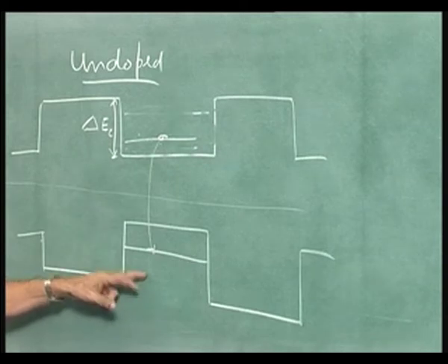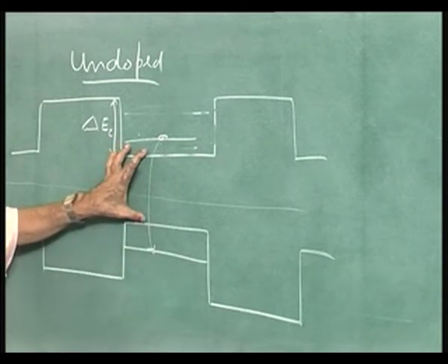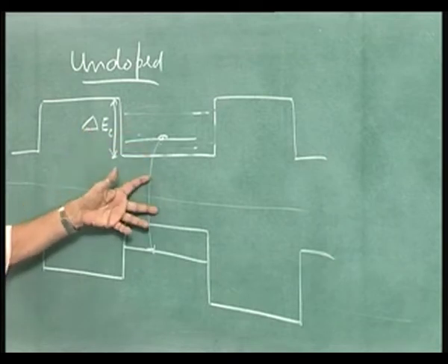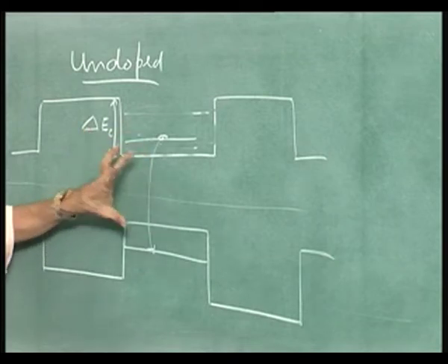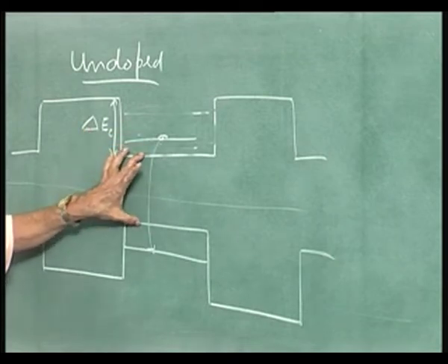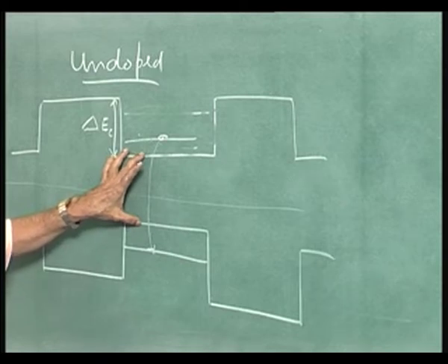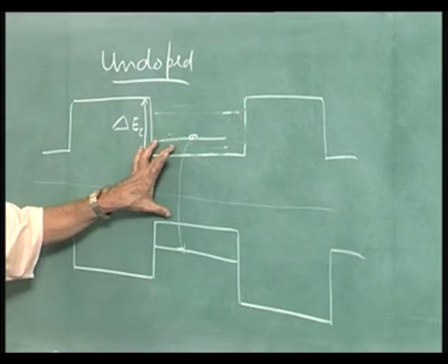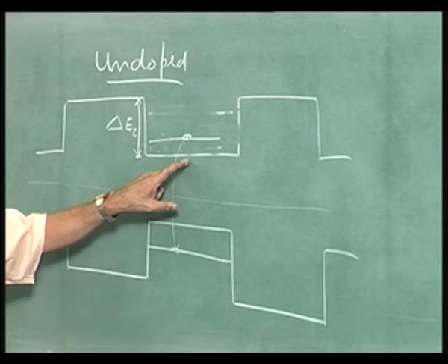If you recall, this is gallium arsenide. I am just showing the undoped situation, which holds good for the doped also. This is 1.43 electron volts. The wavelength corresponding to that is something like 0.87 microns. 1.24 divided by 1.43, that is the wavelength in microns. So, it is about 0.87 microns. Now, there are no electrons here in this case.